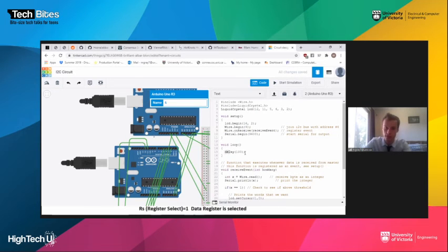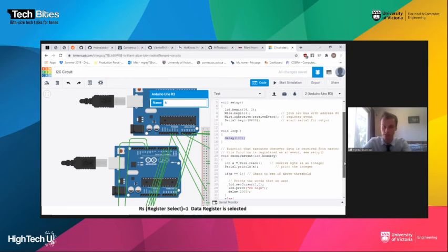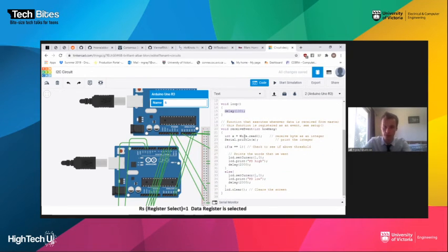And this delay is going to be checking every 1/10 of a second to see if an event has occurred. What this event is doing is reading from the wire whatever int we are sending. It's going to print it for us just to see. And if it's 1, we're going to say that the photodiode is high, greater than the threshold. This is saying we're starting at row 1, column 0. And if it's low, we're going to say it is PD low. So let's see this work.